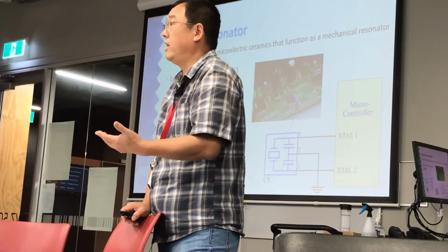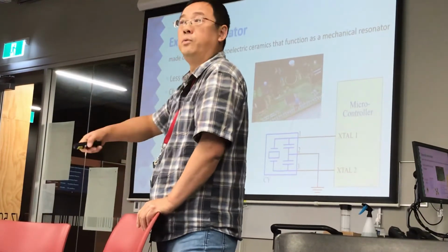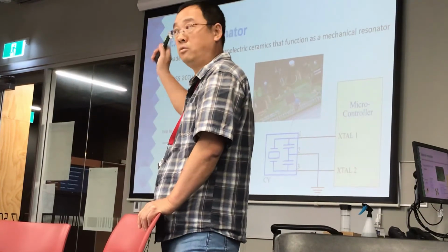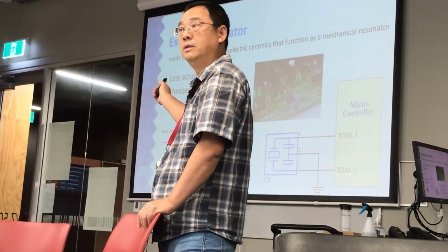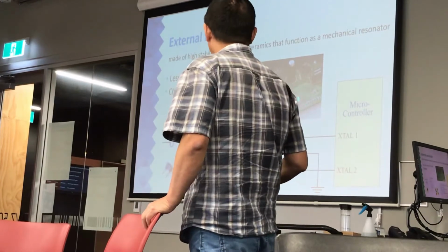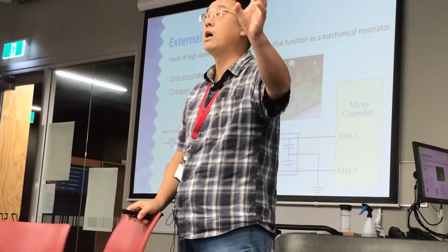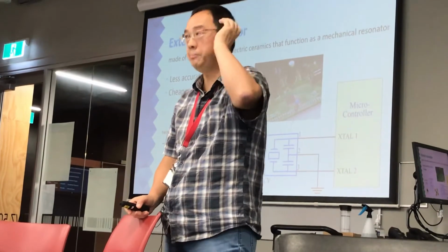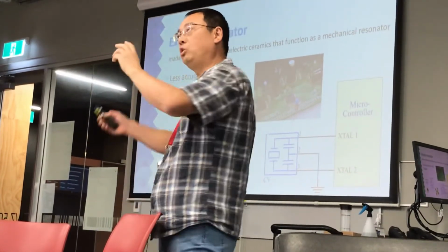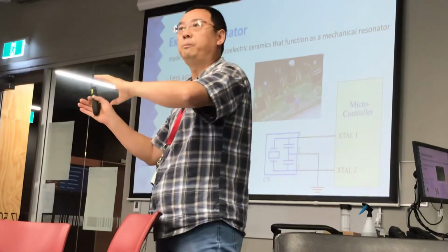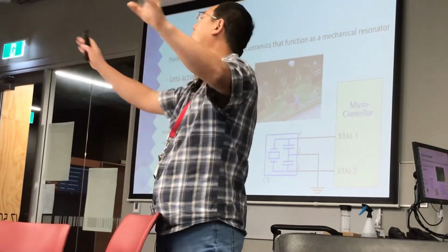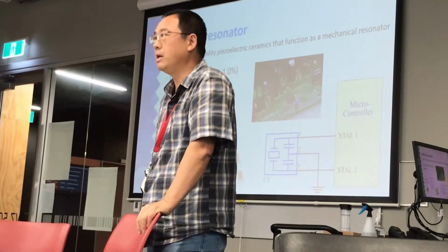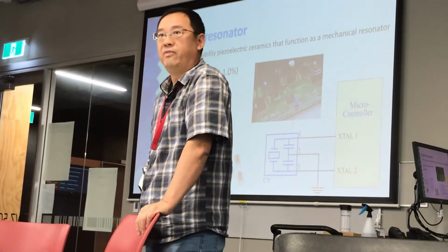That is very fast. It's on, off, 0 1 0 1 all the time. That's very noisy, right? So you don't want this clock too far away from your microcontroller clock pin. If you leave it too far away, you're going to spread this noise all around your microcontroller board.